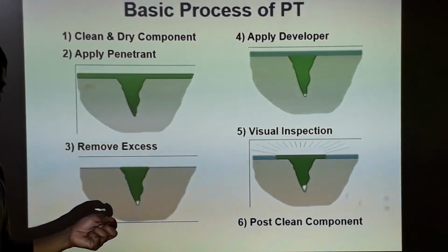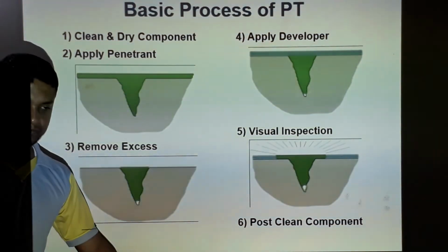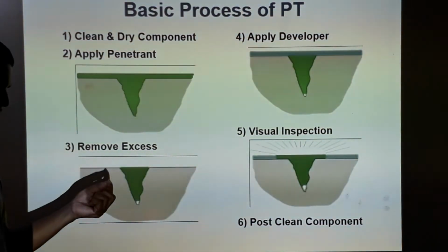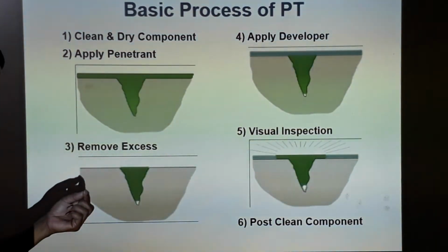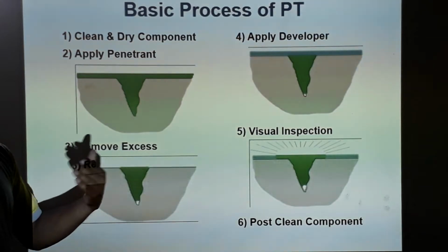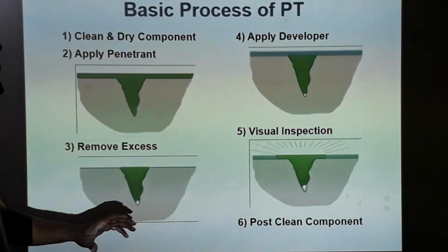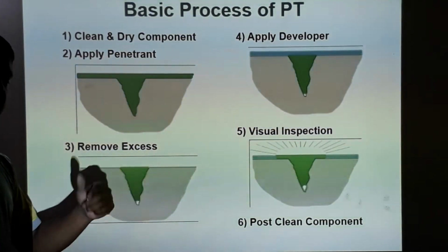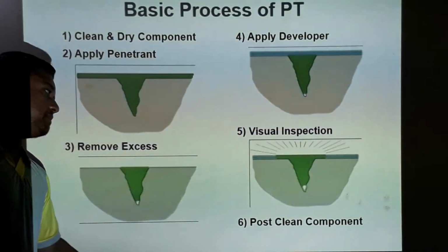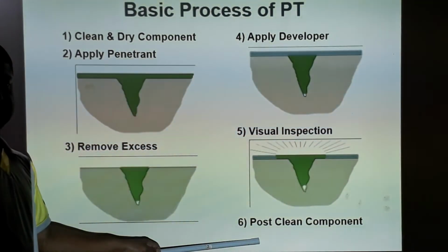Because these residues, especially for aerospace components, when the residues of penetrant material come in contact with some corrosive atmosphere or some other materials, they will create other chemicals that will be harmful to the parent material. So post cleaning of the part is also very important.